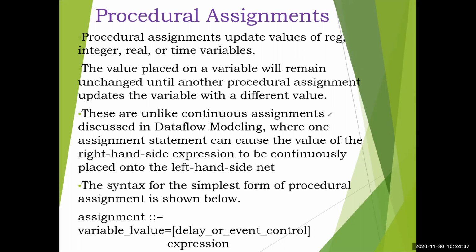This is unlike continuous assignments discussed in data flow modeling, where one assignment statement can cause the value of the right hand side expression to be continuously placed onto the left hand side net. That was done in data flow modeling using the assign statement. Continuously it was placing the values, but here it will work a little differently.